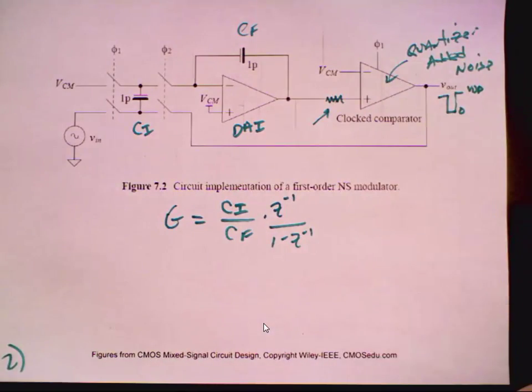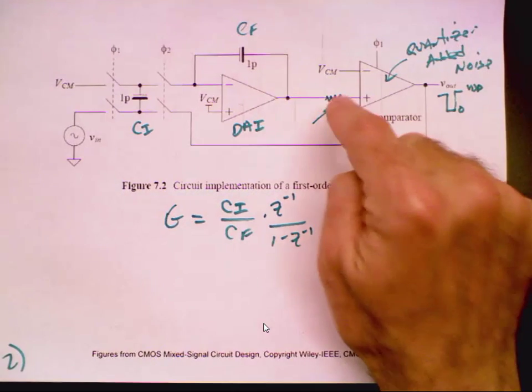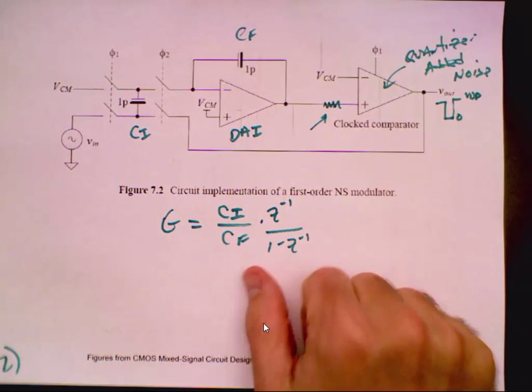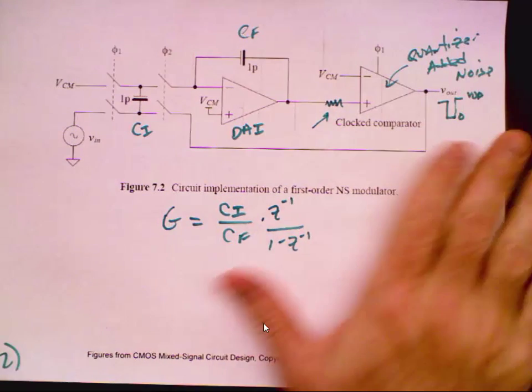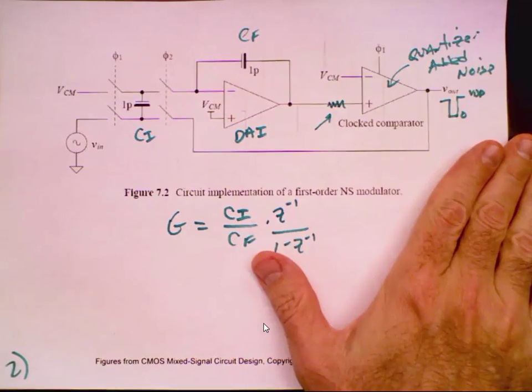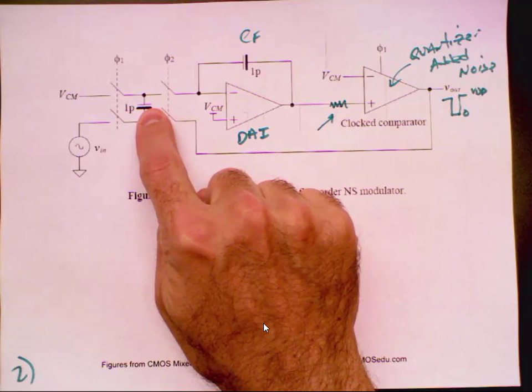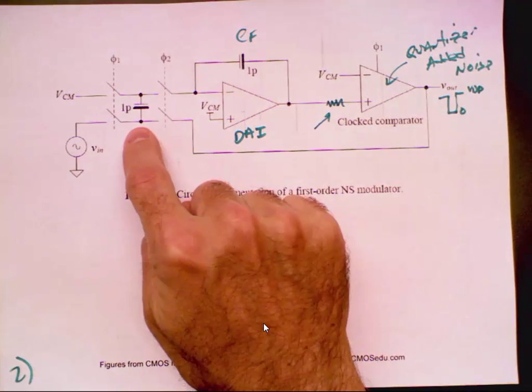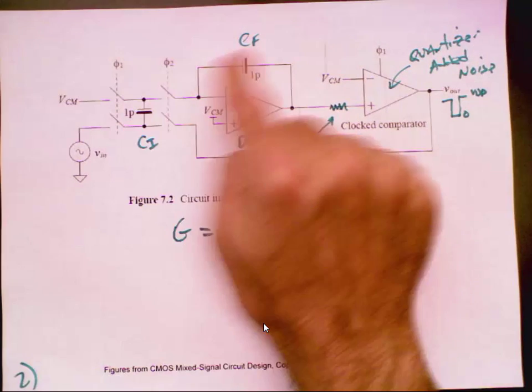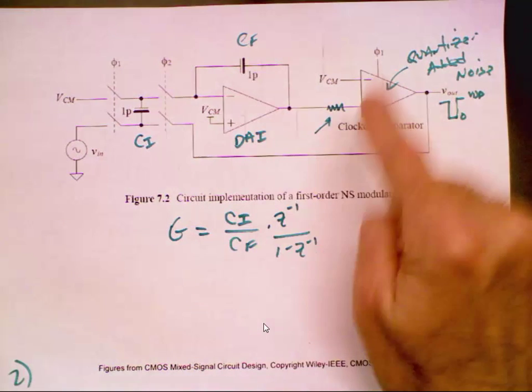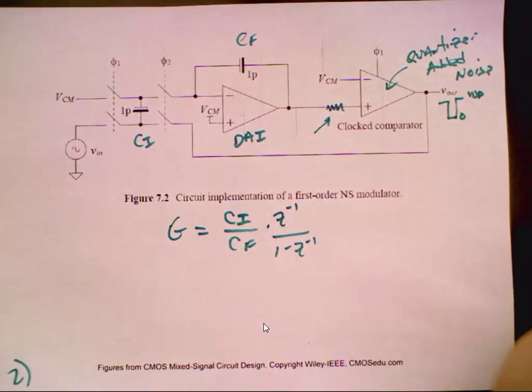Now, what am I the king of? Trivial question. So tell me what I do in this circuit, and we'll verify it in simulation to reduce the swing here. I could adjust this capacitor. Well, either one, right? If I make this one smaller or this one bigger, then I'm going to reduce the signal swing here. Why is that important?